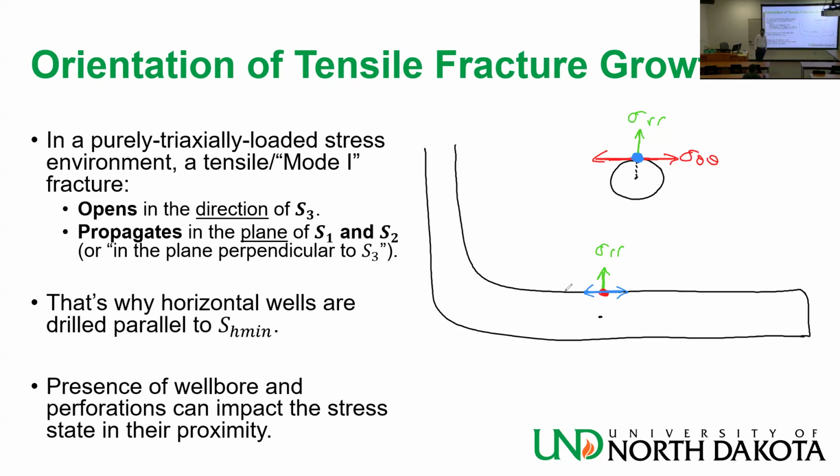People doing research on well integrity care about debonding, the cement not being bonded to the well. Sigma RR corresponds to that. It's the same kind of failure. It's tensile failure. It's when sigma RR becomes sigma 3 and exceeds the minus T, that's when it goes off.